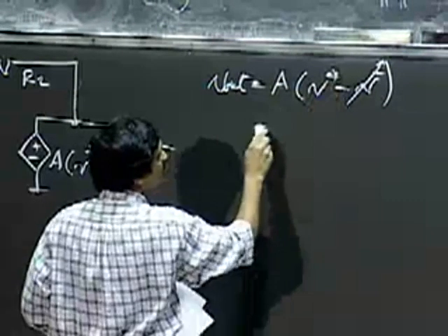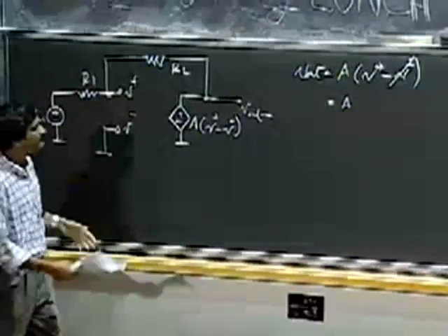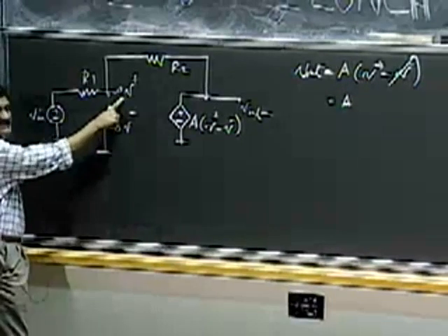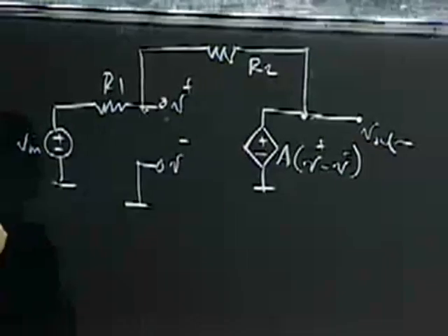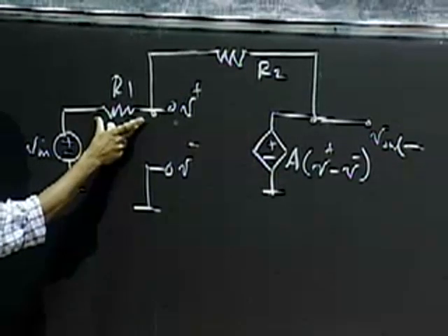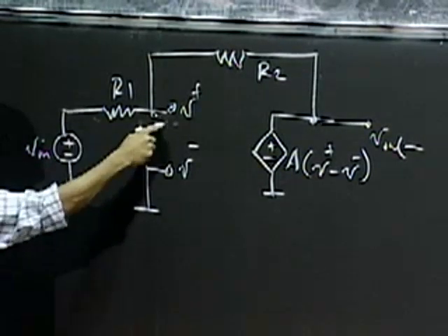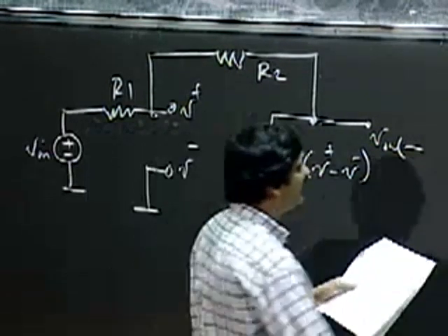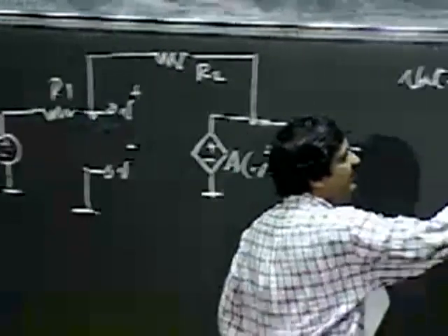So then, let me go ahead and replace V plus with the voltage that relates V out and V in. So what is V plus? V plus is simply the current through this part of the circuit, the current flowing here, times the resistance R1. That gives me the drop across R1. And to that, I add V in, and that will give me V plus. Okay? And then, of course, I multiply this by the gain here. So let me write down that expression.